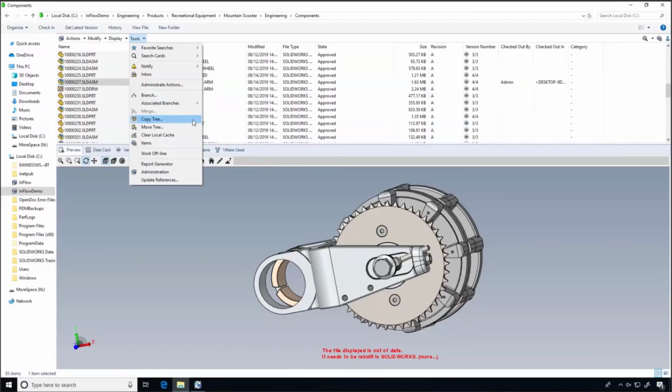There's no reference to it. Branch will create a branch from that file, and you can have as many branches as you want. So what Branch is great for is a situation where maybe you want to try out 3 different designs. You want to try out maybe 3 different holes in this little gear here. Maybe you want to make it more lightweight. Using Branch, we can try out all 3 designs. We could run simulations on it, make sure it all looks the way that we want, make sure it functions properly. And then you can use this little merge tool to put that back to that original file.